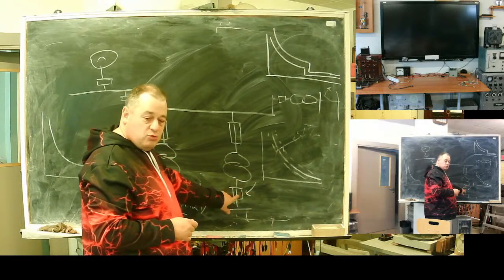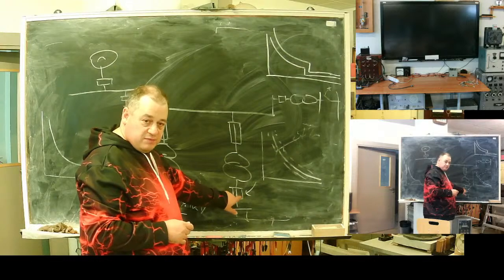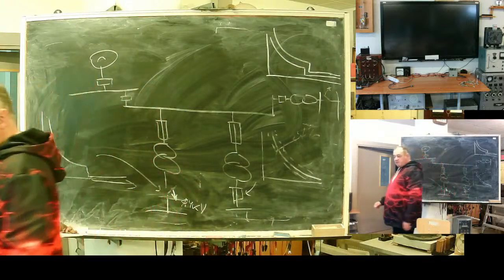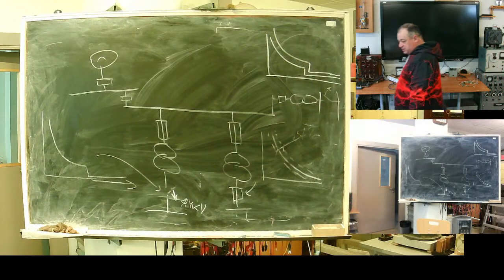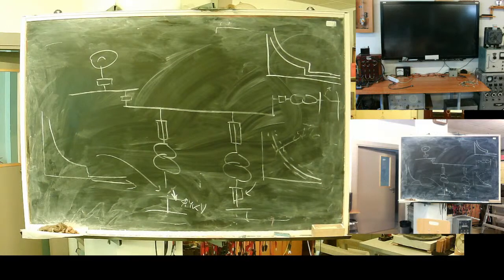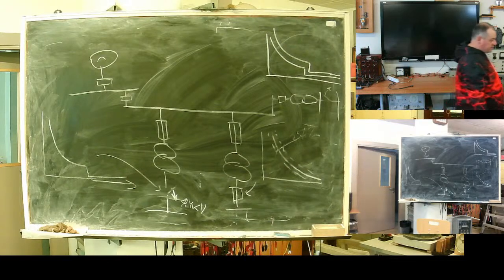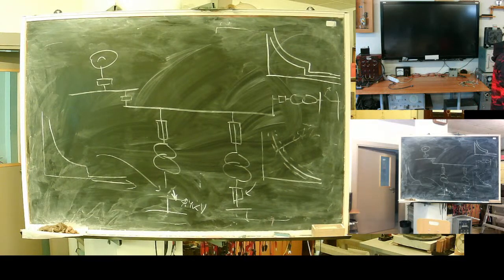Watch at this. You need to coordinate with this fuse. Start from the most powerful client and go down. In the ideal case, you will be able to protect all. But in our climate, it's unrealistic because on the one line we can have a 1 megawatt customer and a 100 kilowatt customer.